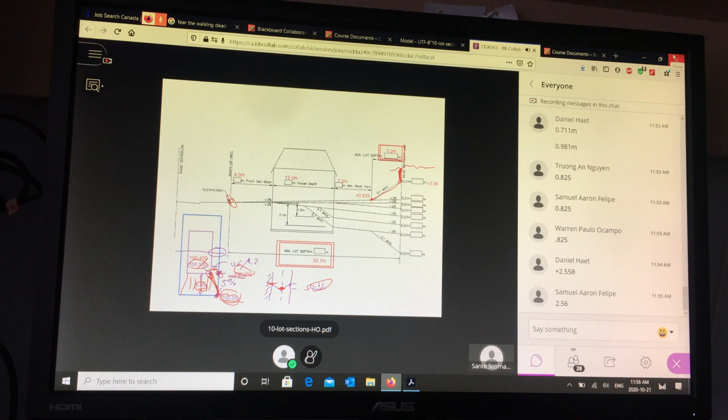If you want all usable backyard, then your wall extends all the way down to here. And that's much higher, much more expensive, and so on. So we use the 3-to-1 slope to minimize the height of the wall. So first we try and avoid it. If you can't, you try and minimize it at the very least. Okay?